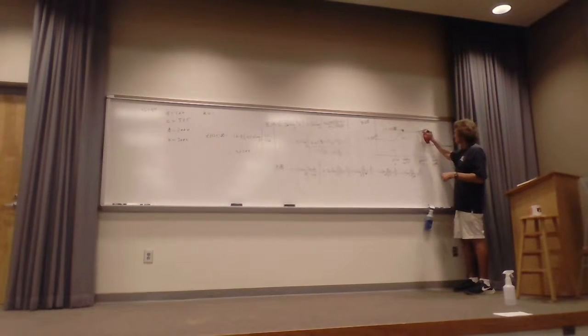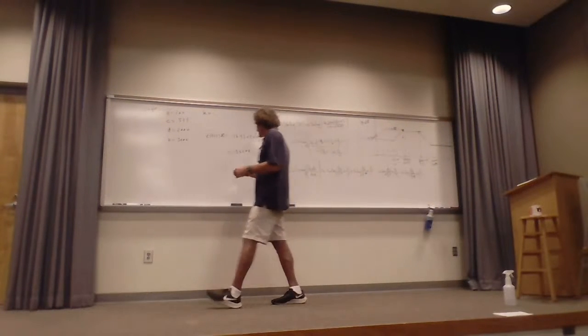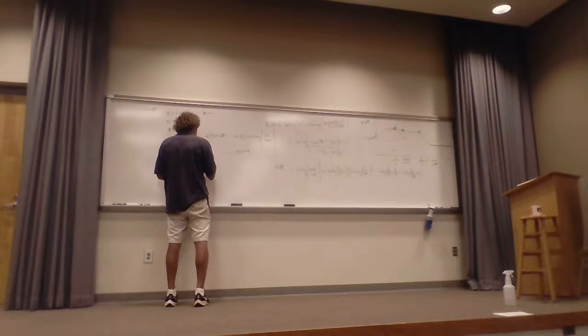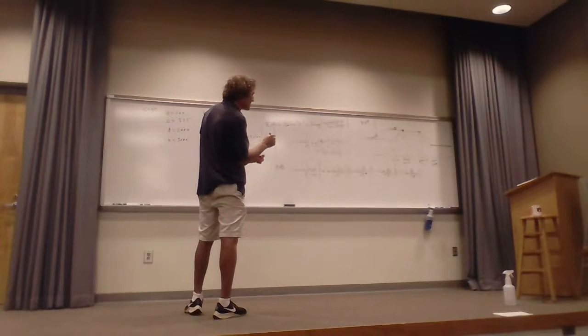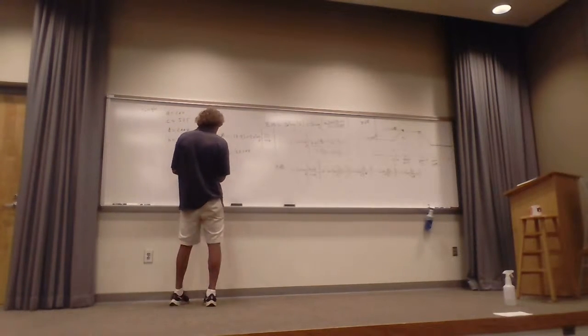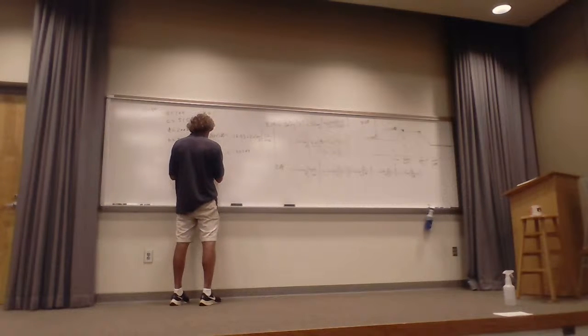Okay, but in this case, it starts going down, right? So if we're here, which is the same point as here, I take that value, and now I'm going to subtract off minus 20 times the log of 3,000 over 2,000. So this is going to be the z of 2,000, not 525. My bad. All right, so now we want the z of 3,000.